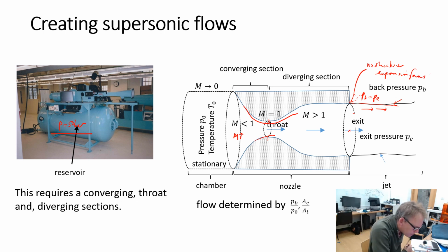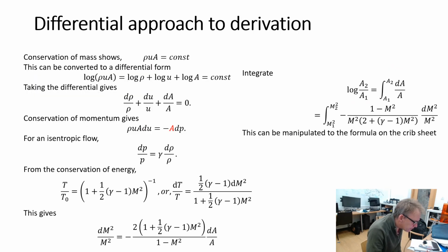Now, what happens with these kind of reservoirs is that the mass is lost, and the pressure differential is reduced. Now, it won't reduce continuously, and it won't change the mass flow rate until the flow is no longer choked. So we'll discuss that next.